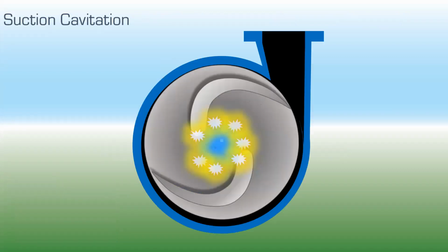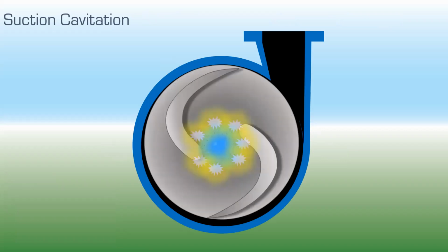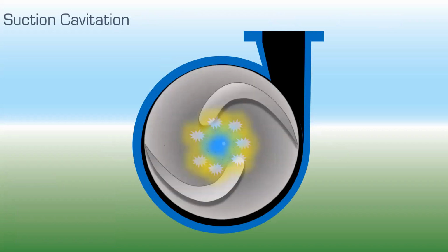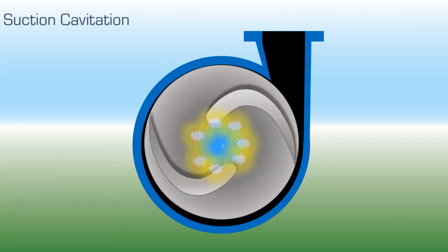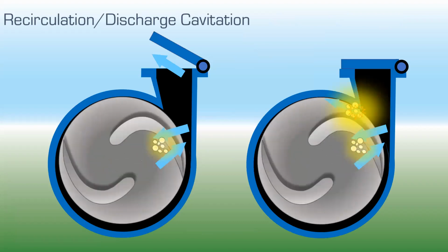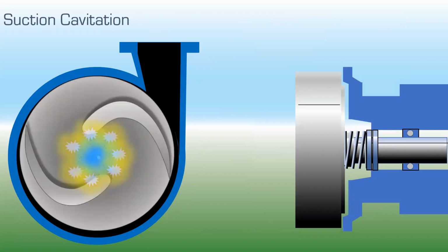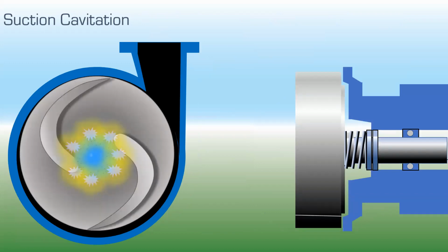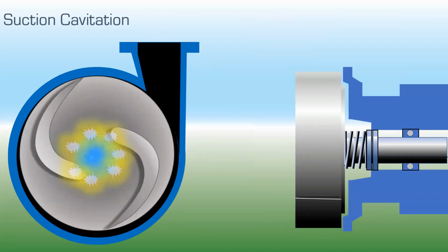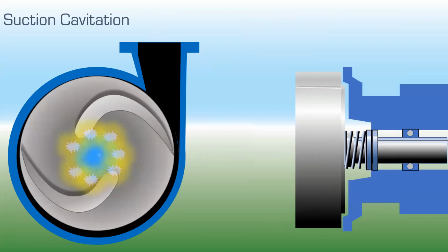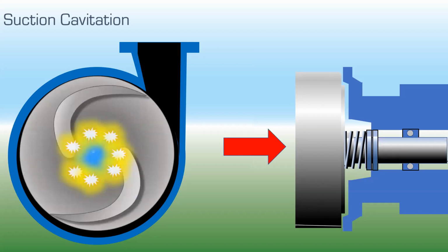We do, yes. Okay, suction cavitation, let's look at it because it is noisier. If you're listening to a pump suction cavitate, you would think for sure that it's worse, but it isn't. Suction cavitation affects the impeller eye. Remember, recirculation and discharge cavitation affect the outer portions. So let's see how that affects the impeller rotating body itself. All these suction cavitation blasts as this vapor bubble collapses, with 200 to 300,000 PSI pressure spikes, are all happening down the shaft itself.